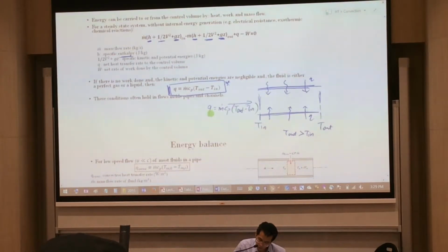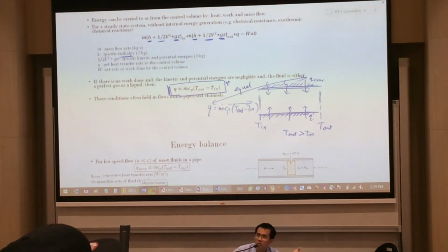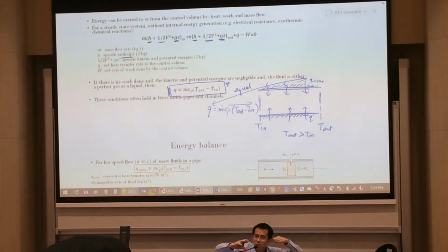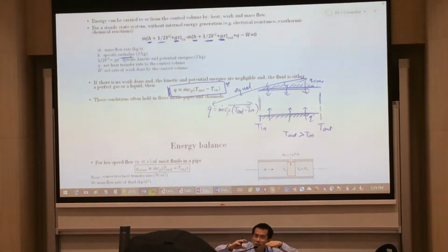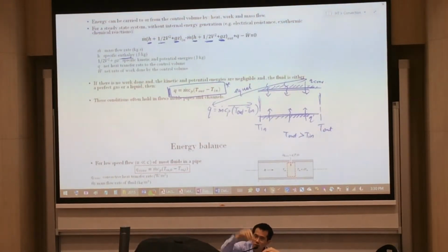So that's to say this Q will be equal to my Q convection that's going into there. These two Qs will be equal to each other, provided that your pipe has got thermal insulation. Now that's a part that I need you to know, right? And this is an important concept. A lot of times it comes up in exams and they keep on testing you on that same thing. Do you understand that if you have a heated pipe that liquid flows through, that liquid will gain heat, and that heat transfer rate is equal to the convection that's going in?